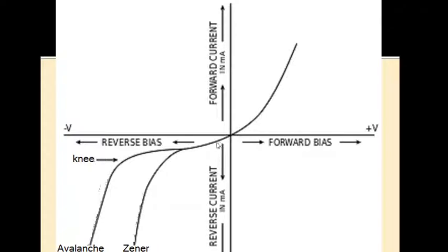When you are applying a reverse bias voltage up to a certain voltage, let us say up to this point, then the Zener breakdown will be triggered, and a larger number of electrons will be tunneled through the depletion region, and the conduction electrons will suddenly be enhanced, and therefore a sharp increment of the Zener current, or the reverse bias current. That is what a Zener breakdown is.